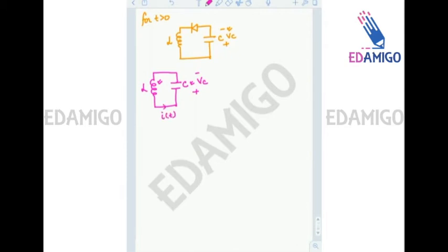Okay, right? So before solving this, we will solve this. That will help you in actually solving LC parallel circuits also. So since inductance was initially charged from top to bottom by 10 amperes current, taking the Laplace transform of this circuit, we get that